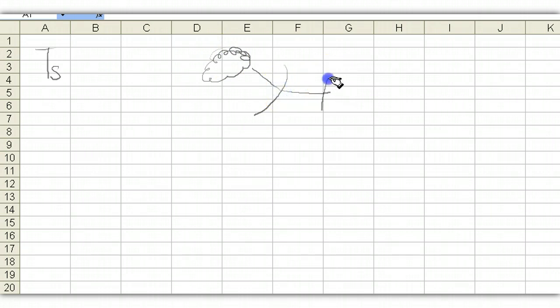And to make things a little more complicated, we have what we call a low noise amplifier, and typically that's abbreviated as LNA. And this thing delivers energy to a load, typically a receiver. So let's go back to cold sky. Let's assume that we're doing a CubeSat and we're off the horizon maybe 30 or 40 degrees, and we're not looking in any particular constellation. We're just looking at typical background stars, and at this frequency, at this elevation, we typically think that the noise equivalent temperature is 30 degrees Kelvin.